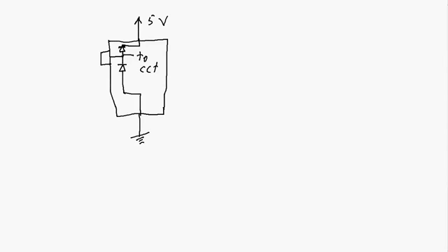And similarly here on the second diode, if the input voltage gets above 5.3 volts, 5.7 volts, again depending on the forward voltage of this diode, this diode becomes forward biased and it clips the voltage that's going to the circuit to about 5.3 to 5.7 volts and protects the circuit from any over voltage.